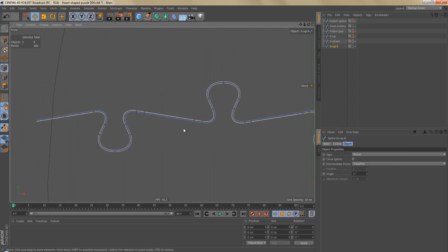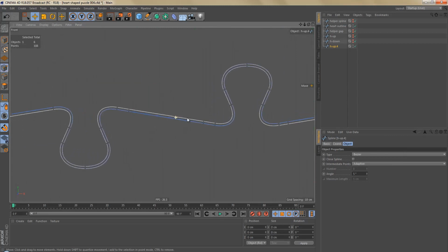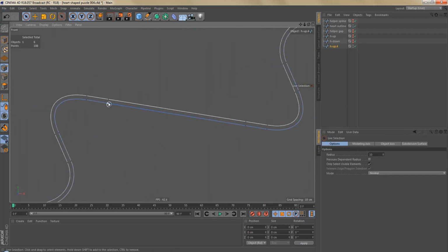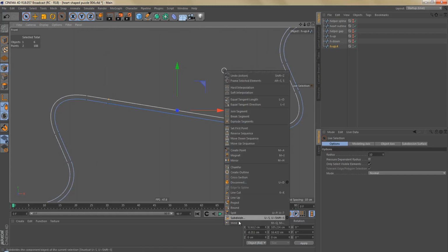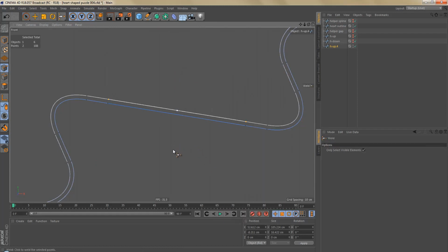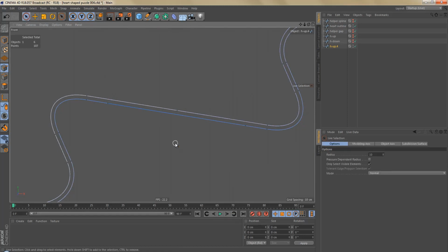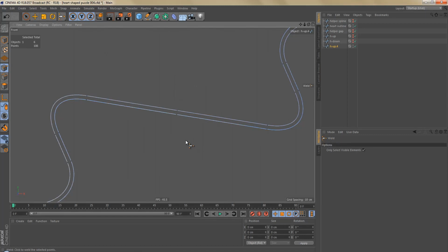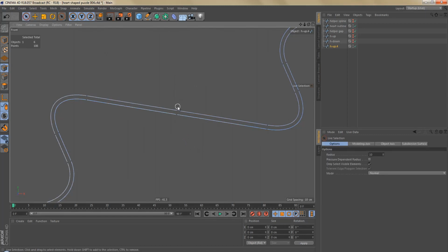And of course the segments are not yet connected, so let's switch off snapping, grab one of the selection tools, and I'm going to select these 2 points here, right click and weld them together by left clicking anywhere in the viewport. And if you hit spacebar, you can go back to the last tool you used, which is the Lite selection in this case. And I'm going to select these points, hit spacebar, weld these points together, spacebar, select these 2 points and delete them.